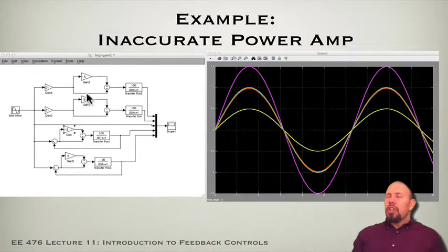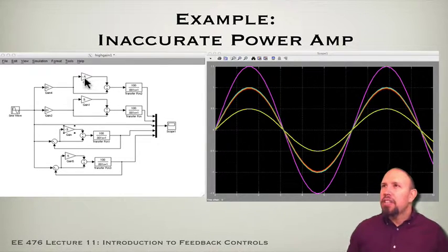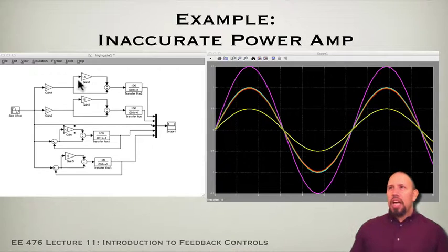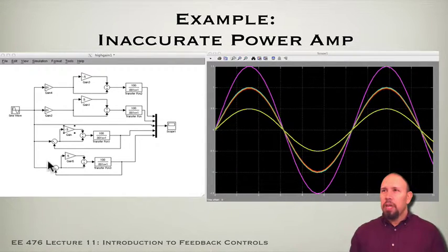Okay, so the 2 open loop designs are at the extremes of the uncertainty. Remember, we have plus or minus 50% uncertainty. So this is minus the uncertainty, this is positive the uncertainty, and we do the same thing here for the closed loop design, with minus uncertainty, positive uncertainty. So we're actually doing 2 simulations for each case, for the static open loop and for the P controller.